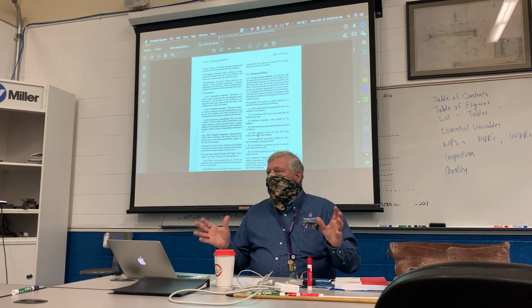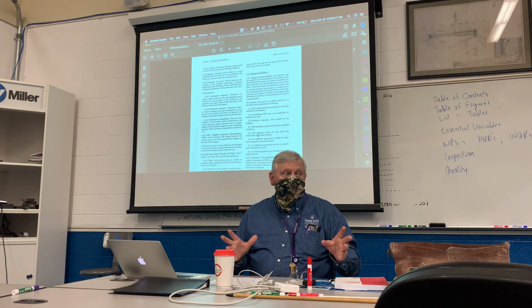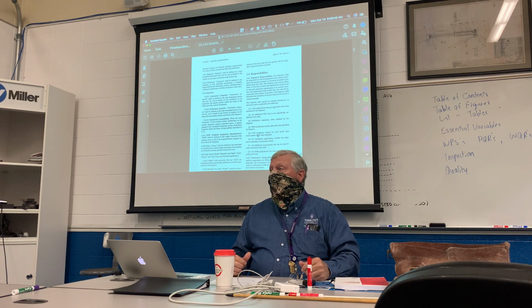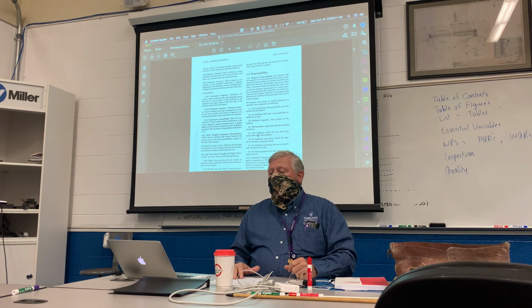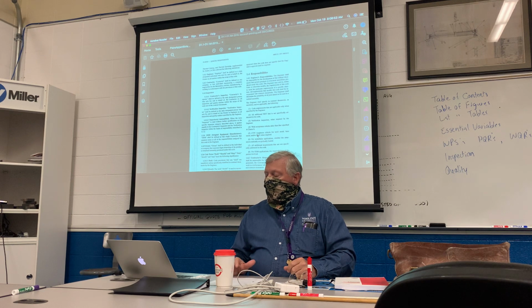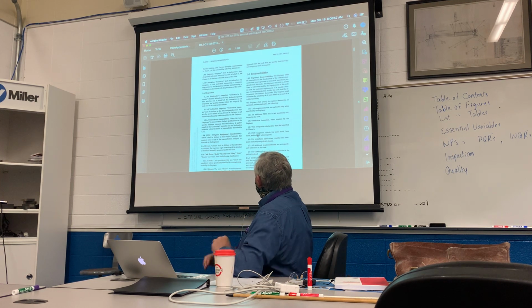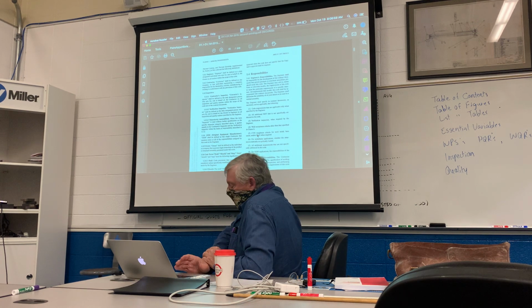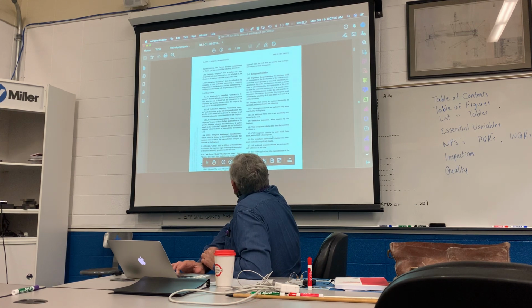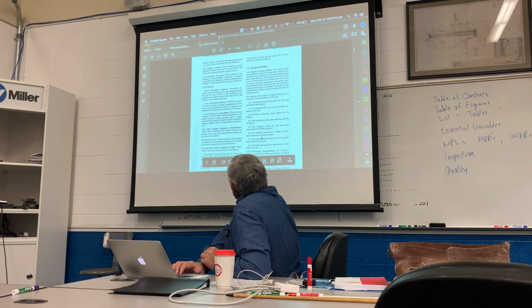If one of the welds fails, then somebody's going to come back and ask why did it fail? Because we didn't do Charpy V-notch. Well, then you're in trouble, and your insurance company's going to pull you up. So Charpy V-notch toughness for weld metal, base metal, or HAZ when required.